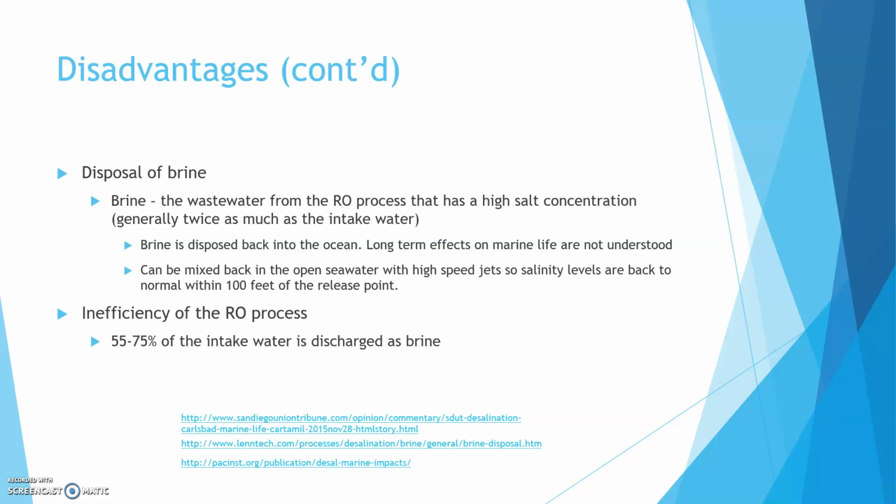In order to accurately measure the performance of an RO system, you need some basic parameters. You should know the basic parameters such as feed pressure, permeate pressure, concentrate pressure, feed conductivity, permeate conductivity, feed flow, permeate flow, and temperature. I think it's better to understand all these terms to design an RO system.